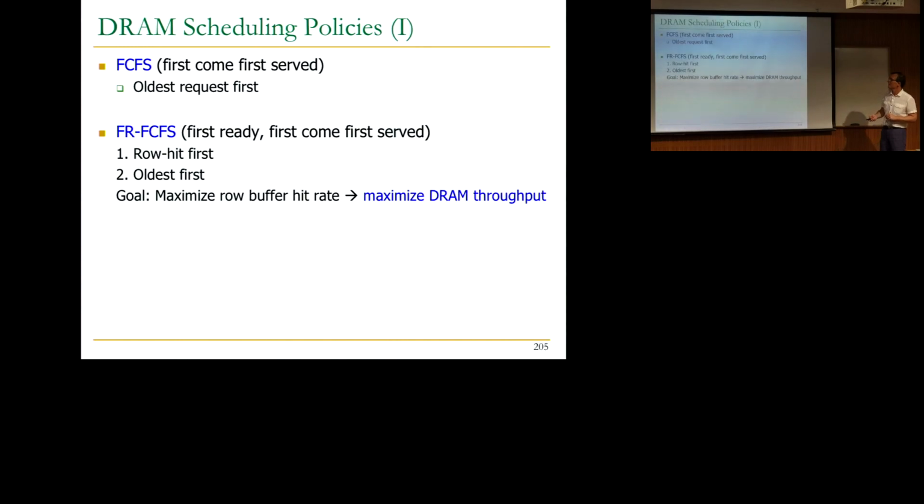Okay. So scheduling policies, let's talk about that briefly. So what request to schedule first? The first one is really not a scheduling policy. What is a policy? First come, first serve. You don't do anything. You just serve whatever comes to you first. And actually, there were some old controllers that used this in the past. I don't think a lot of controllers are using this at the moment because it doesn't take advantage of this row buffer that we discussed, right? Row buffer is a natural cache in DRAM. As a result, many controllers move to this sort of scheduling policy.